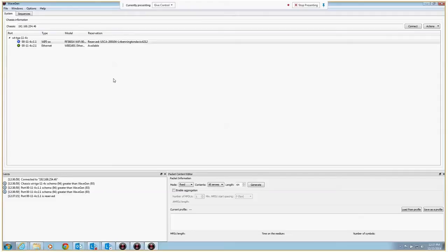A vector signal generator only works by playing out a file that has been previously created in software. This tool does not use any pre-created IQ file. It simply uses the real-time packet generation of the card, and you're using this application, WaveGen, to simply describe to the card what sequence of packets you want coming out.